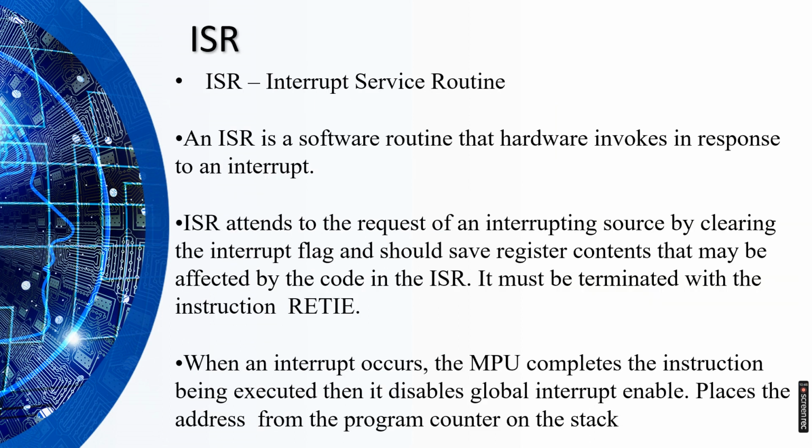Moving on, we have ISR, which stands for Interrupt Service Routine. An ISR is a software routine that hardware invokes in response to an interrupt. ISR attends to the request of an interrupting source by clearing the interrupt flag and should save register contents that may be affected by the code in the ISR. It must be terminated with the instruction RETFIE.